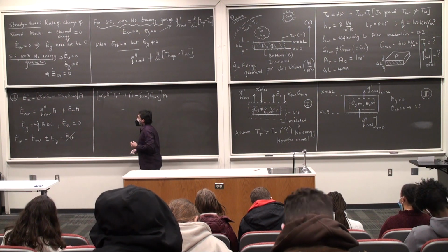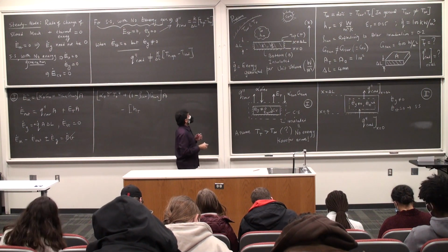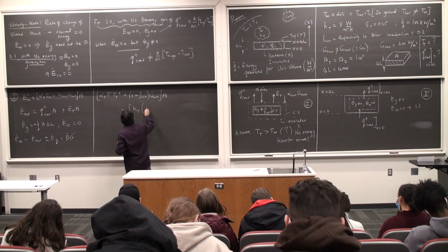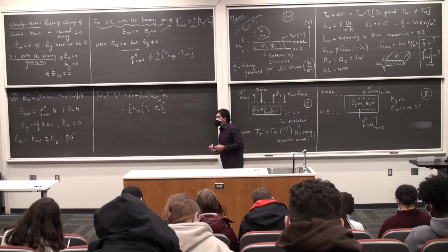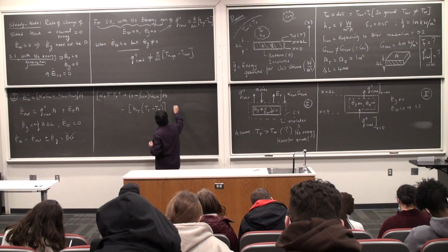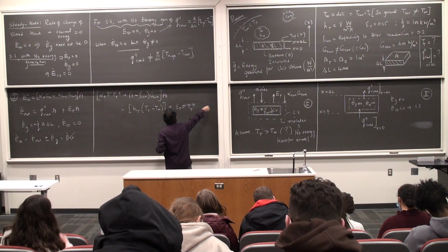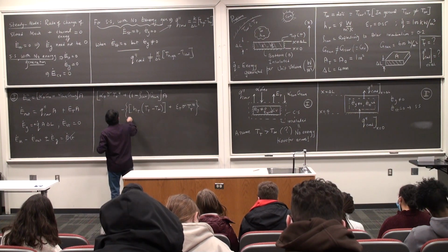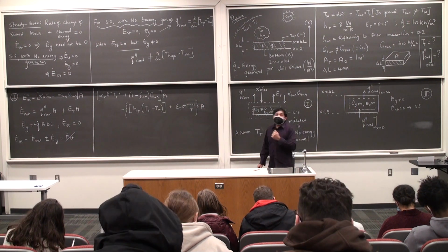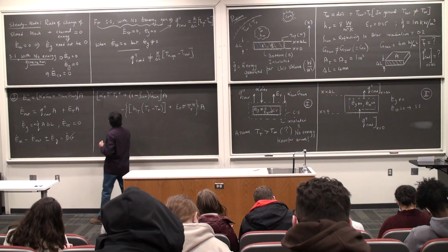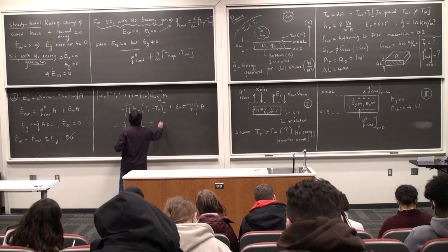minus convective heat flux, h top, is what I had assumed, I guess, times T top minus T infinity, I'll multiply by the area eventually, and plus epsilon T sigma T to the power 4, multiplied by area, plus energy generation, because it's a positive quantity for us, plus Q dot A times delta L is 0.